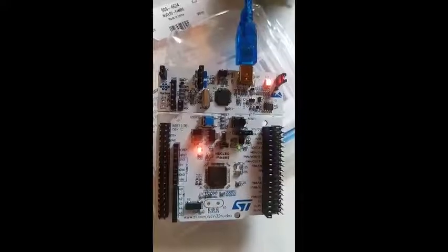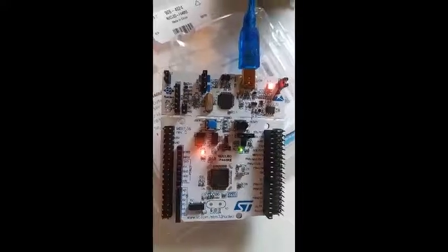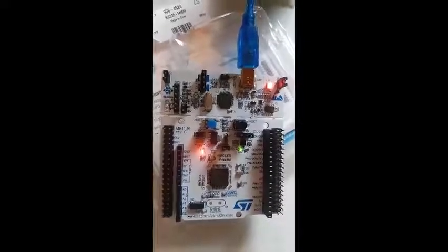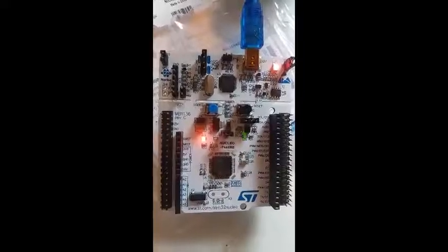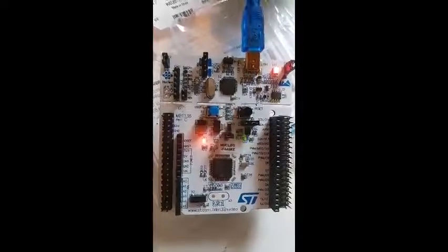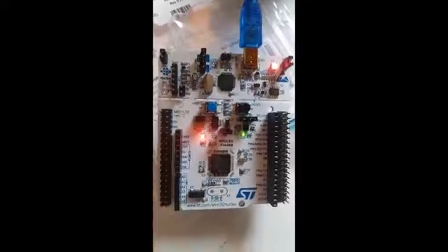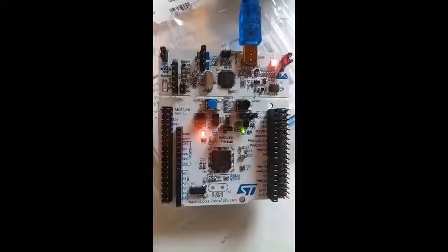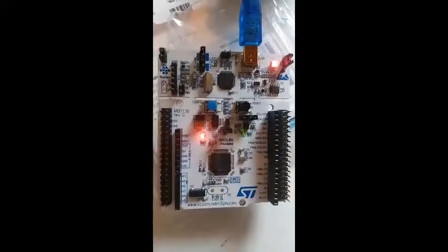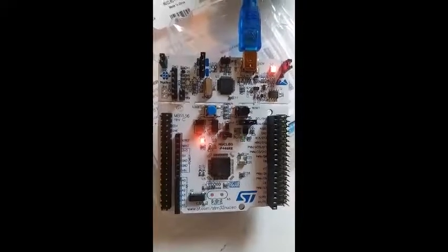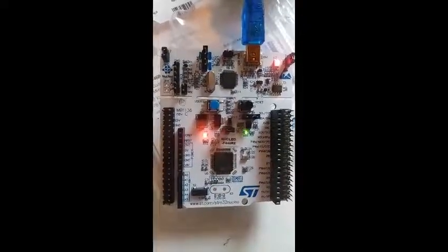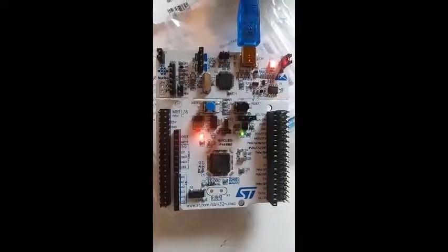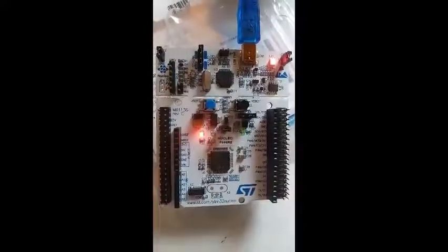Again, with the delay, I discourage using that, because it takes a lot more resources than just using the interrupt. You're basically using the polling method on that one, which could slow down your program, and it's not ideal for a big scale project. So interrupt is much more efficient, and good. The nice thing with this STM32, there's a lot of timers, and you could use a lot of timer interrupts. That's it for the timer interrupt.